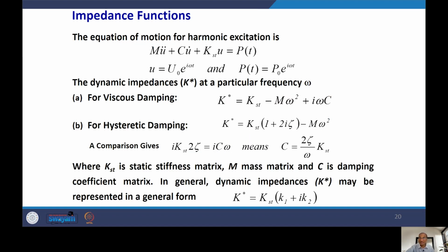Now, when we talk about SSI analysis or normally in soil interaction, we come across a term called dynamic stiffness or impedance functions. So this is the same thing. Let me write it down here. This is dynamic impedance functions, and this is also called dynamic stiffness. You have a static stiffness, and this is exactly the same thing whether you say impedance functions or dynamic stiffness.